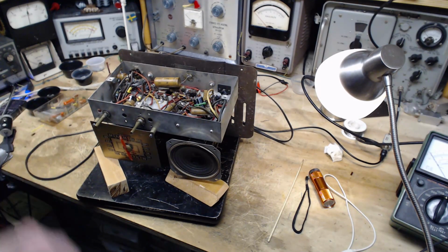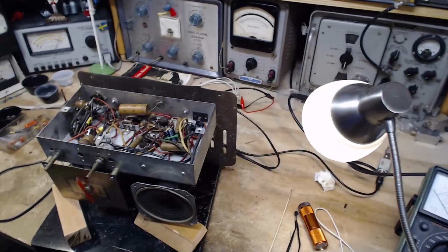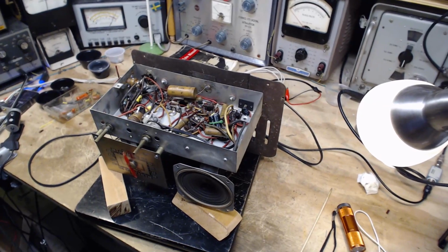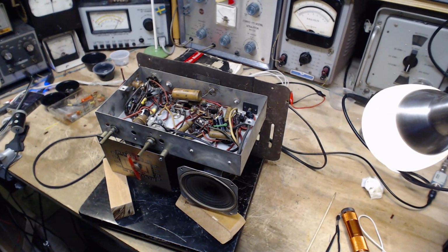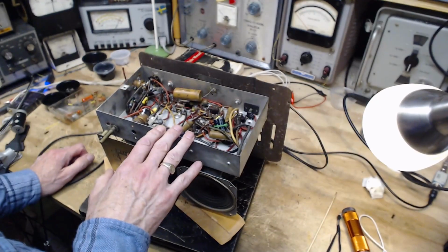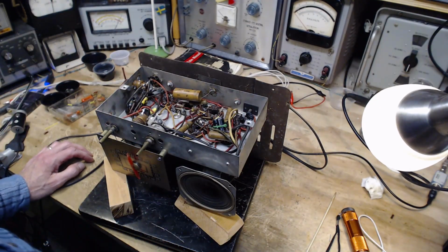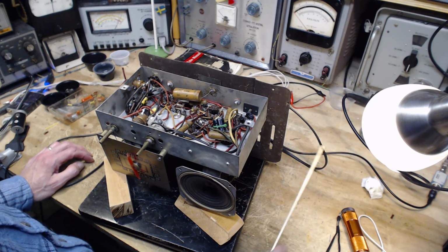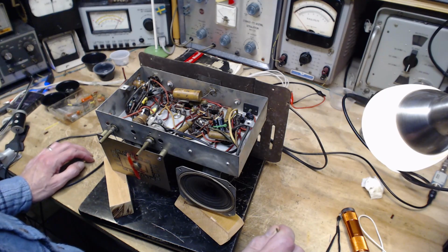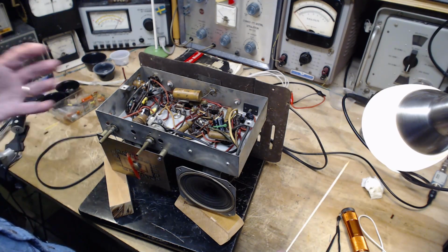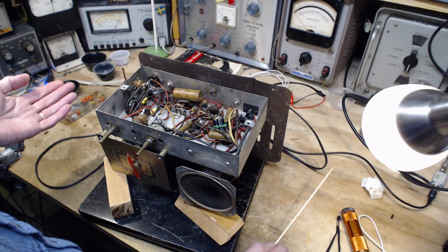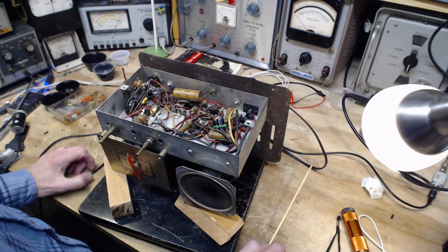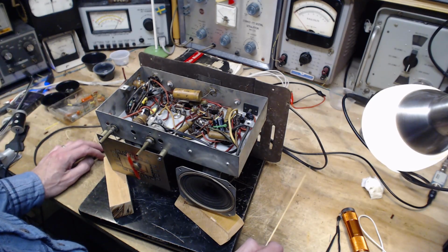Okay, now, what to do next with this radio that might be interesting and revealing. With the radio working fairly well, it's kind of going to be hard to find something to change in here that's going to have some dramatic effect on it. The next capacitor I think I want to go after could be called the AVC capacitor. And this capacitor usually resides beyond a very large resistor in the AVC circuit. And I'll explain that in a minute. We'll look at the schematic and I'll explain what I'm talking about.